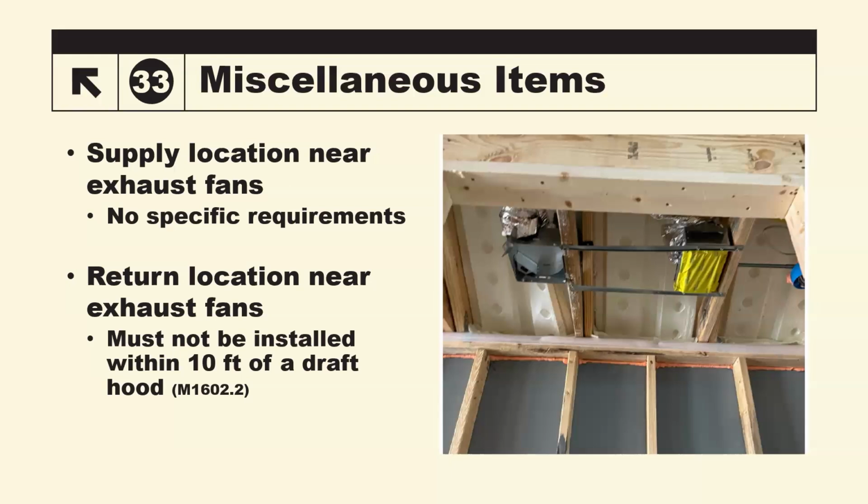But after talking this over with him, I said, look, there's nothing saying that you can't. The best practice is I wouldn't recommend the throw being towards the vent. In other words, if I was installing it, I would have turned that vent 90 degrees and just had that vent grill facing either the outside wall or the wall that's actually an opening of a door. You probably wouldn't want to do that because now you're blowing air out of that room itself. You're not conditioning the room that it's in.